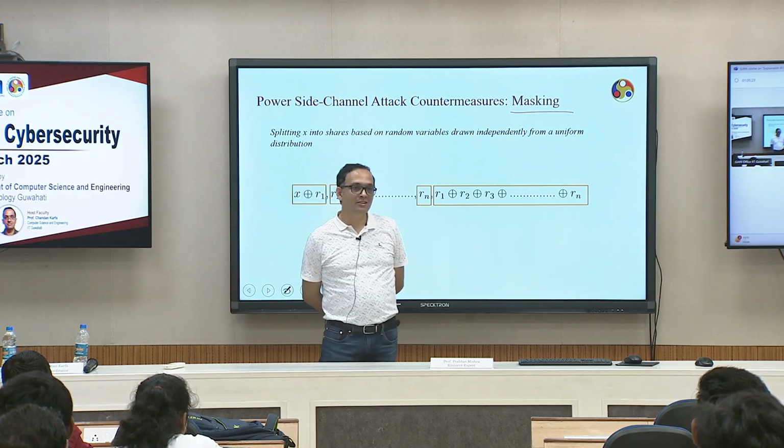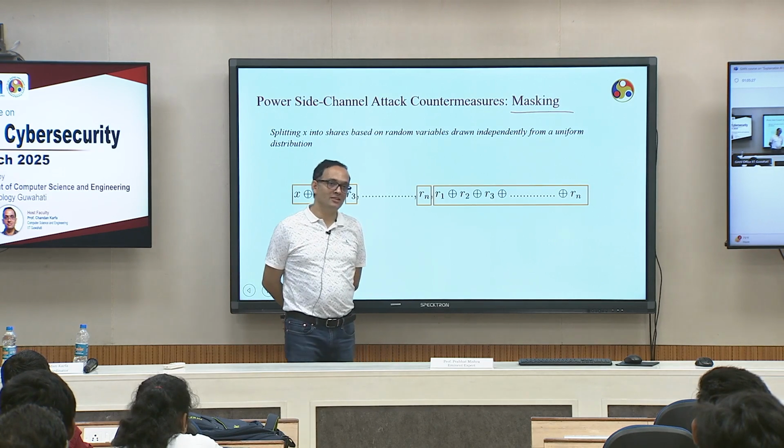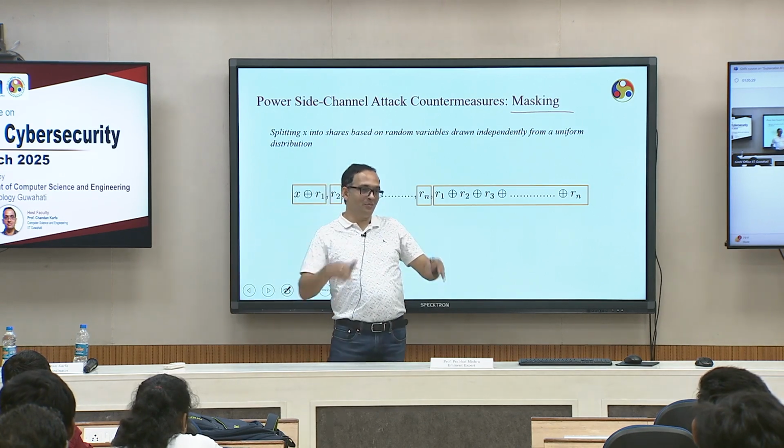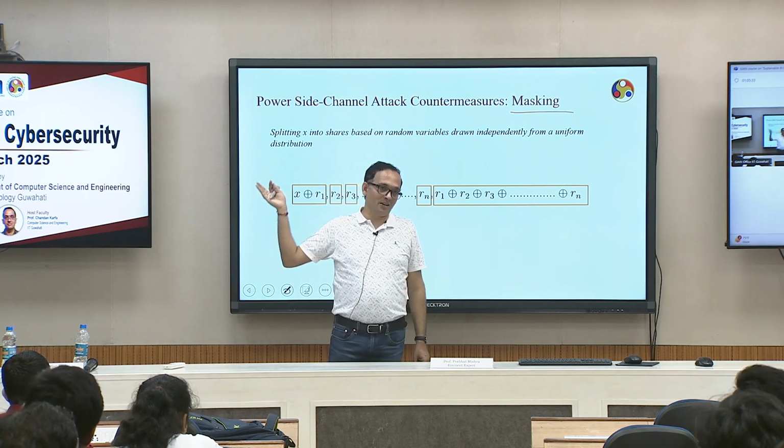Sir, by doing masking, will it increase the resource power consumption for the system? Exactly. So, it's like we have constant IoT devices where the resources are constant. So it's a very good question. Masking has huge overhead. I will show you today that masking on AES can have 27x area overhead. So, original masking AES may be say 100, it will become 2700.